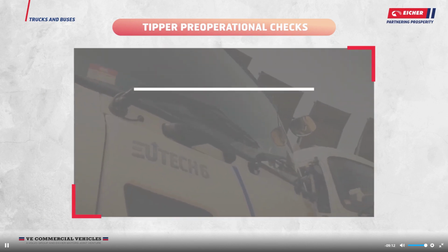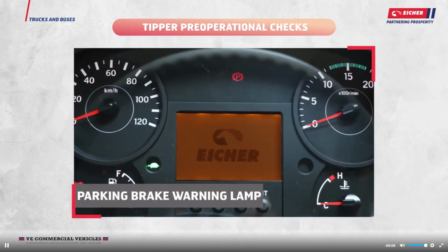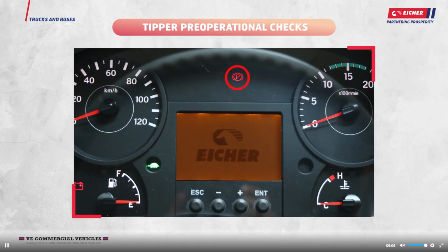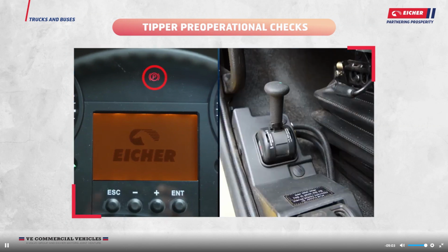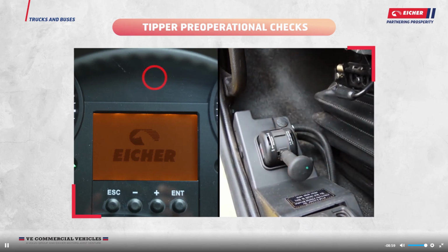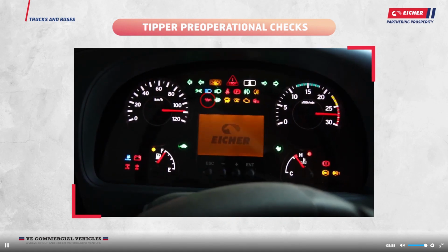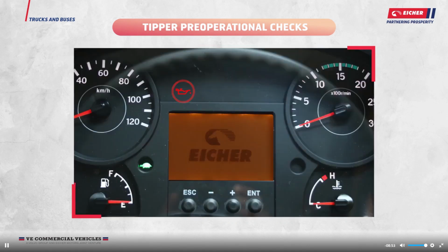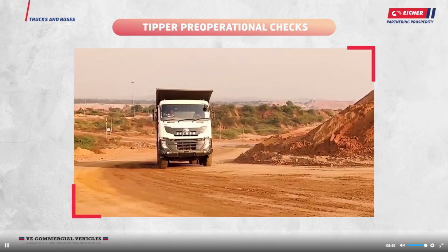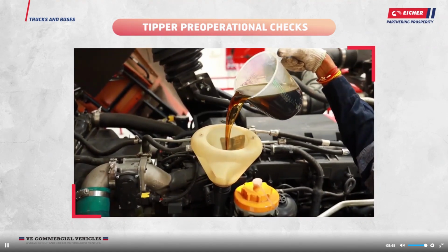Now check the warning lamp and gauges on instrument cluster. Parking brake warning lamp. Check warning lamp is on when parking brake is in applied condition and light goes off after releasing the parking brake. Check engine oil pressure warning lamp is on when the ignition key is on. Ensure that warning lamp goes off after engine starts. If the lamp is on while driving, in such case, check and top up the oil level.